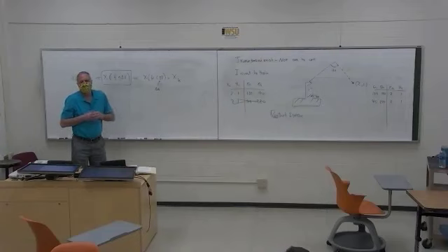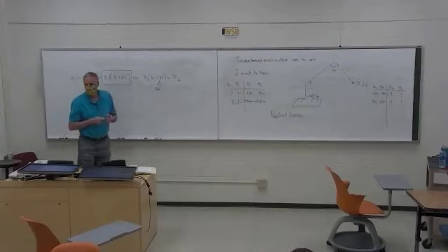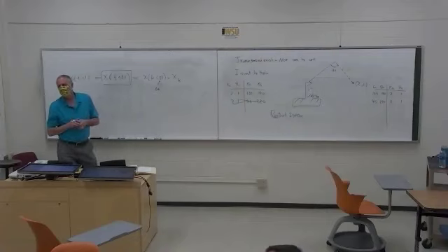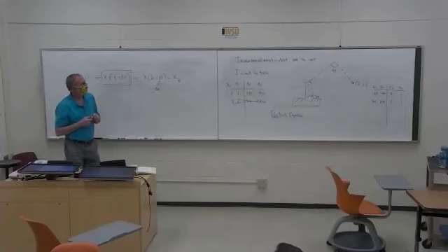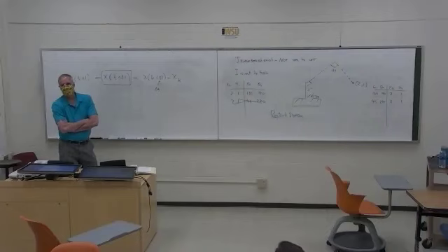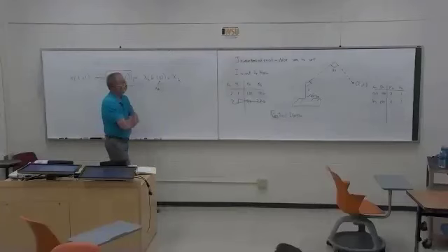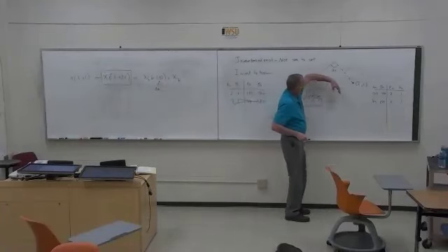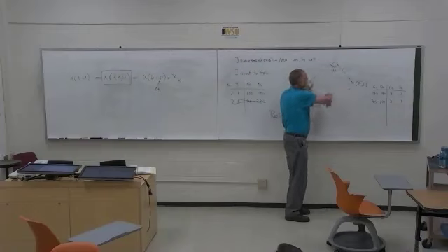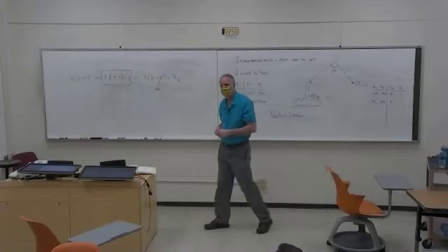Yeah, well, it's obviously also a good example of system modeling, like we did. Could we also just, would it take 2 different neural nets, or might it just be other methods, for both cases of the domain to restrict it in either direction? So like make sure theta 2 is greater than 180 degrees as opposed to being less. Yeah, there's no reason why you couldn't have a separate network for each domain. You'd have to have some kind of strategy to figure out which one you're going to use in what situation. Yeah, because maybe you're moving from one position to another position and there's something blocking that, so you might actually want to drive the robot to the other inversion.